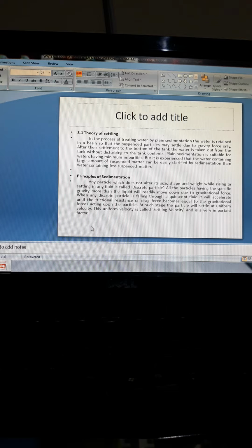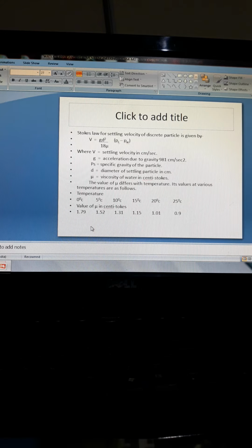During this period, when the water is kept still without any movement, it loses its sediments, that is the suspended and settleable particles settle down because of the properties of these particles, like size, shape, and density, and also the specific gravity and viscosity of the water. These particles are pulled to the floor or bottom of the sedimentation tank.